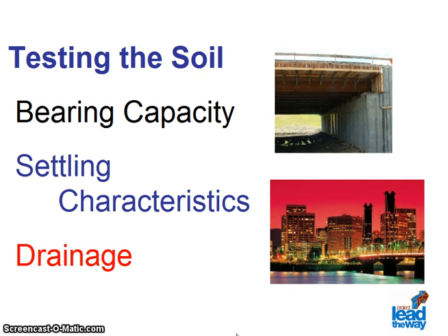Testing the soil informs the engineer about the bearing capacity of the soil. This is the soil's ability to carry the load without any failure within the soil. It can also be referred to as the stability of the soil. The load-carrying capacity of the soil can vary with the strength of the soils and the method and magnitude in which the loads are applied. The amount and rate of settlement for the foundation can be estimated for a certain known soil type. The building can then be designed to accommodate a certain amount of settlement.